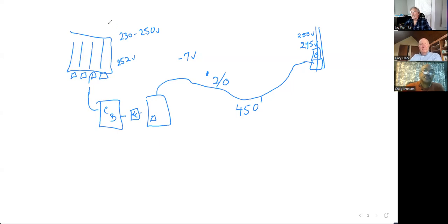So that kicked up with voltage rise, the inverters outside of the tolerance, it was right on the border, and 4 of them it exceeded. So what they did is they were able to adjust the tolerance range within the inverter remotely from California.